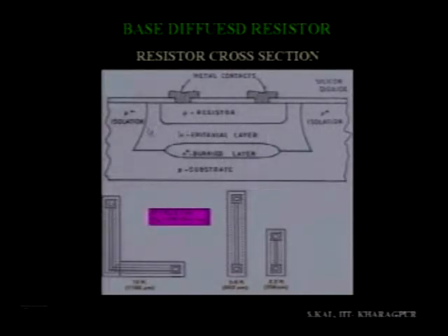And after that, when the island is created, along with the base, the resistor diffusion is also made. Clear? Just like base diffusion, resistor P diffusion is done here, and after that we don't diffuse any emitter here. Rather, you open a contact here and in this region another. So now from here to here it will form a diffuse resistance.